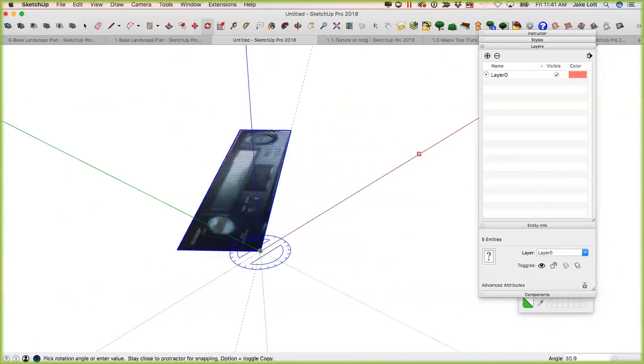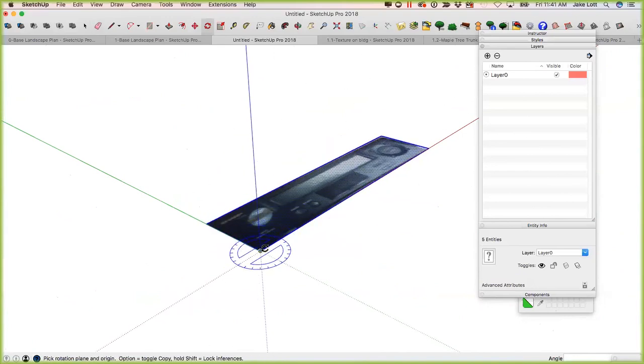So obviously it doesn't look like much of a VCR, right? And we're just going to move it to the origin point. And I'm going to use my rotate tool by hitting Q. If I just click once, it sets down that position so that I can find where my first rotation point is.